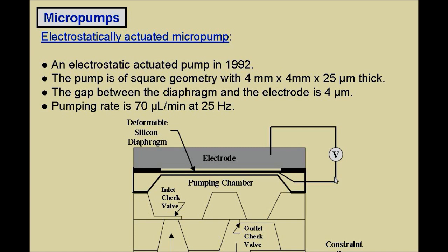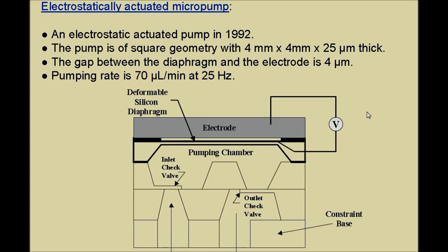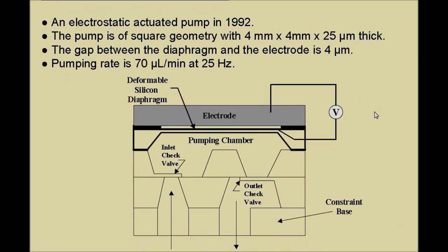These types of requirements are plenty in industry, where you need to suck a fluid or a gas and release it at another point, but you have to do it all with pressure. So creating the pressure, sucking and exiting are requirements in plenty of applications, and that too at the micrometer level. So you can use a simple micro pump with electrostatic actuation. Probably you are familiar with the capacitor that we discussed for producing electrostatic actuation. Again, we are going to recall that here.